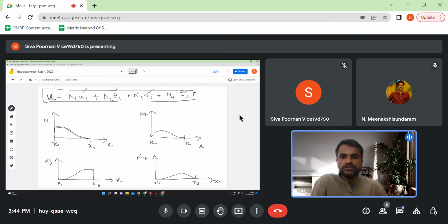By the way, I would like to emphasize that even though this looks very similar to what we had done while finding out the stiffness matrix, where we were giving unit displacements, the difference is that while giving a unit displacement at one end and making all other displacements 0, what we were doing there was finding the end forces and end moments, not the deflected shape. The shape functions are not with respect to forces. It is only a kinematic problem.